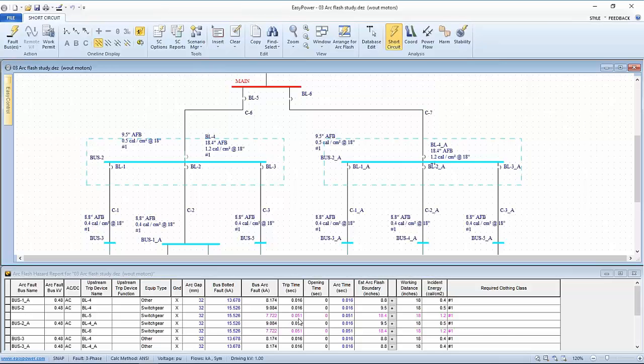The magenta type shows the 85% arcing current calculation. The dark type under this arc flash fault and trip time report, the dark type reports 100% current. And that is controlled in our short circuit options, which I'm about to display. So again, this is where the results are shown, where the control is made.